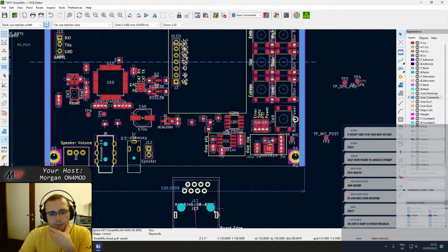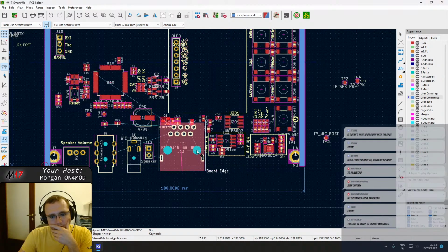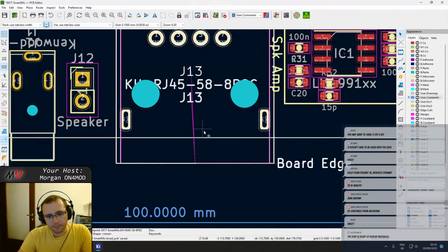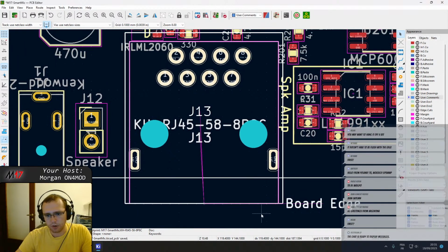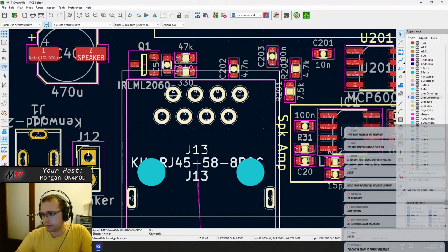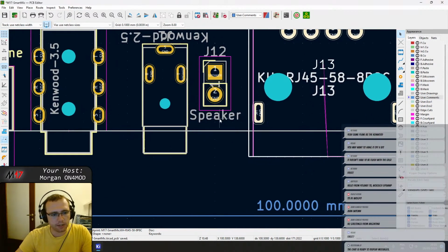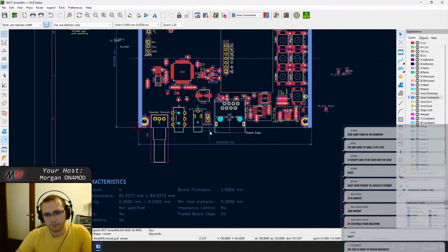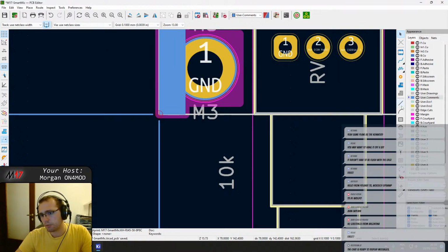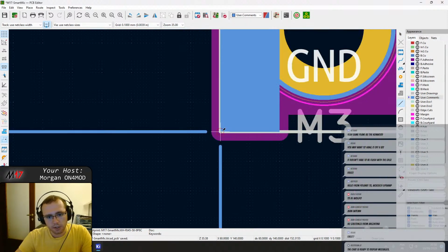It can actually get out a bit. You're right. I think I should hang it by 1.6 millimeters, maybe about the thickness of a board, so that it goes flush with, or same plane as, those. Okay, let me just draw a line 1.6 millimeters away from here.